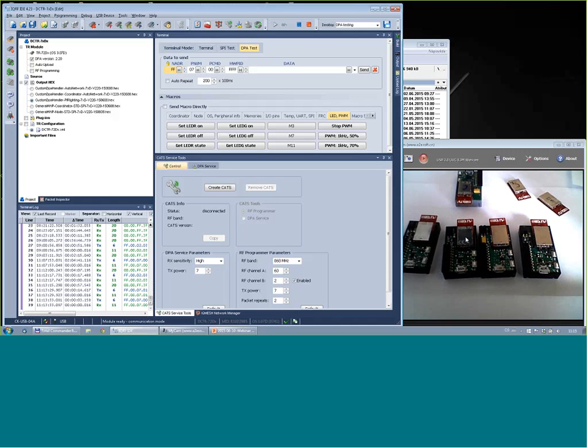For example, in street lighting, where you want to use also some movement detectors, the communication from the coordinator should be done during the day when you are not using the peer sensors. And when you are using the peer sensors, you should avoid the communication with the mesh network because there could be a collision and you can get false results.